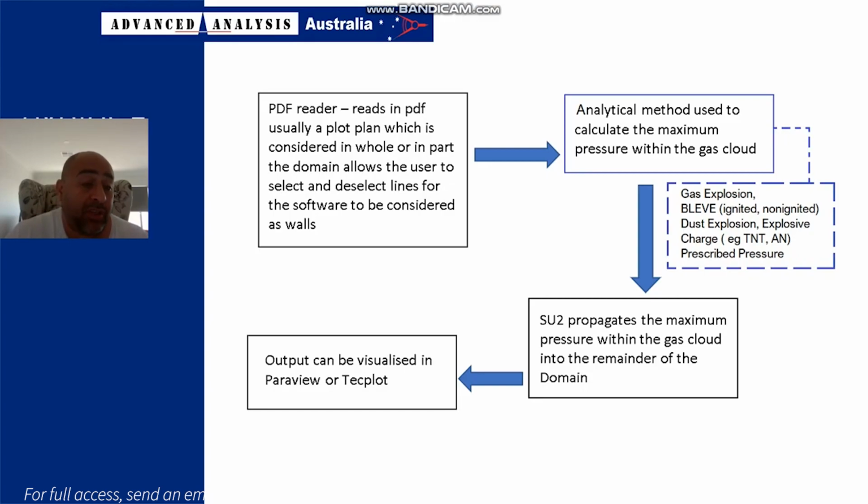It's run in a 2D fashion. This is deliberate because SU2 can run in 3D, so you can configure SU2 to run on detailed 3D geometries. There's no need for that, and in fact all CFD software has traditionally been dissipative for explosions, and so to not be on the underconservative side, SU2 is configured in a 2D simulation.